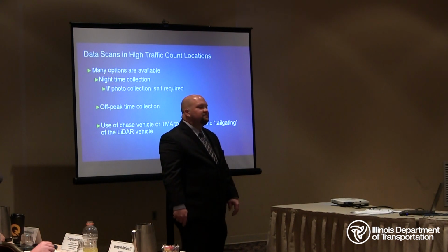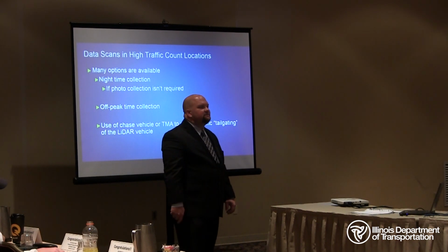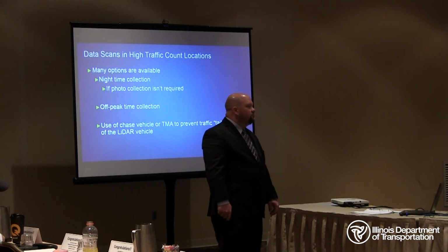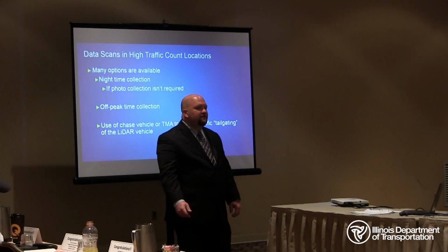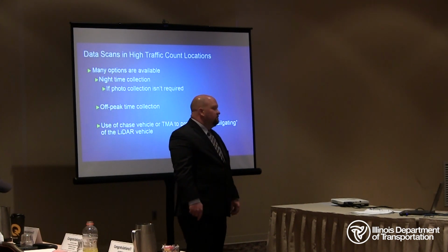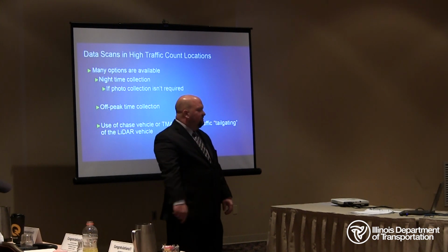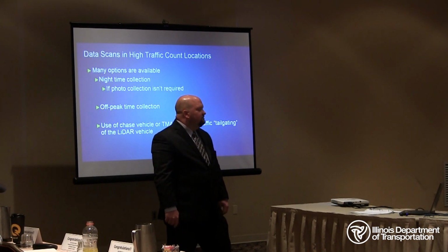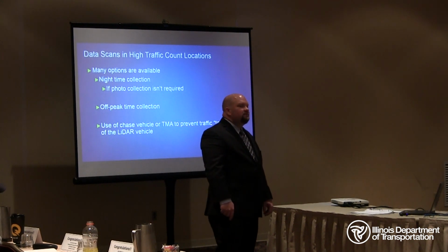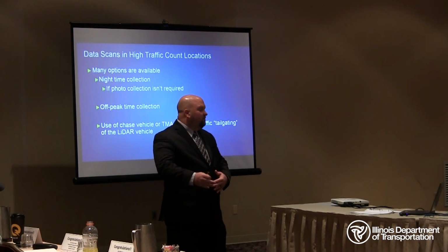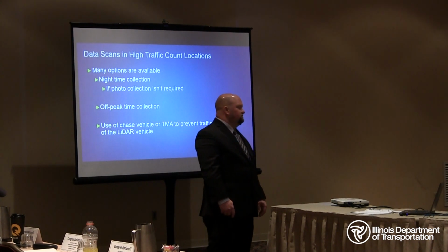If we are doing data scans in high traffic count locations, there's many options available. Nighttime collection is a big one if photography is not required in that contract. You can utilize off-peak collection time when rush hour is not an option. You can also utilize the chase vehicle or TMA to prevent traffic tailgating the LIDAR vehicle to interrupt the point cloud data in certain situations.